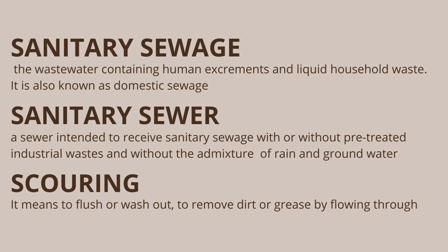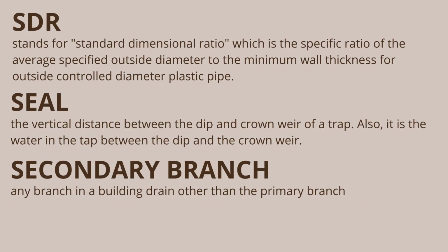Scouring. It means to flush or wash out, to remove dirt or grease by flowing through. SDR. Stands for Standard Dimensional Ratio, which is the specific ratio of the average specified outside diameter to the minimum wall thickness for outside controlled diameter plastic pipe.